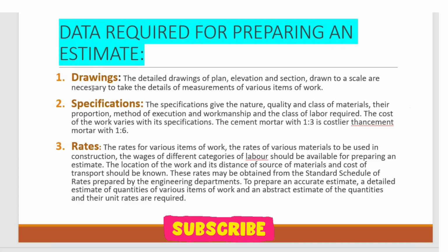Then the next important parameter which we need to discuss is specifications. Okay, the first one we have discussed. Specification gives the nature, quality, and class of materials, their proportions, method of execution, workmanship, and the class of labor required. The cost of the work varies with the specification. The cement mortar with 1:3 is costlier than the cement mortar 1:6. So specifications are again very important. What is the specification? What is the necessity of creating this specification? That we will discuss elaborately in our next video. But it is also an important part.